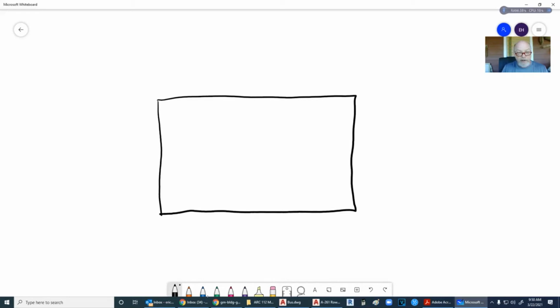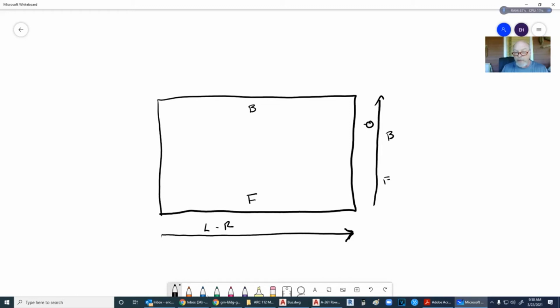Everybody did the same thing. If you're looking at the floor plan and this is the front and this is the back, everything went left to right as you were reading, and from front to back. Even interior walls always went left to right, front to back. That way all of our studs, if you stood over here and looked in there, basically all of these walls, even in the centers, should have lined up. You should see one stud down through there instead of a whole bunch of studs that aren't laid up.